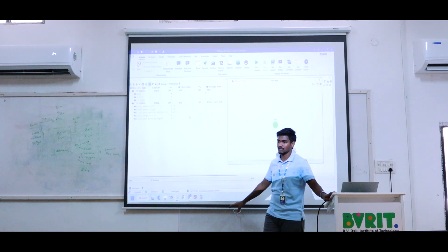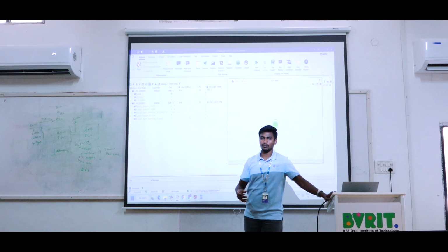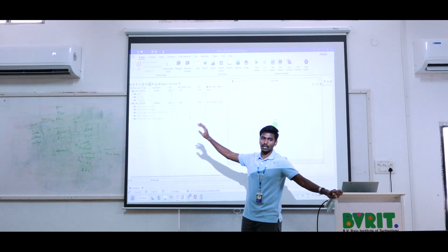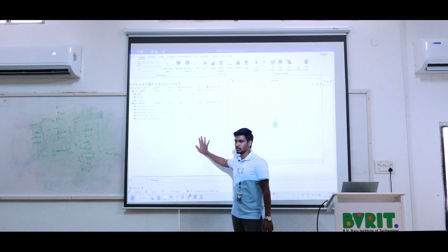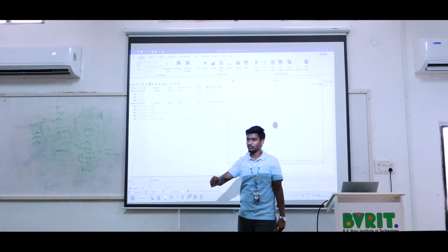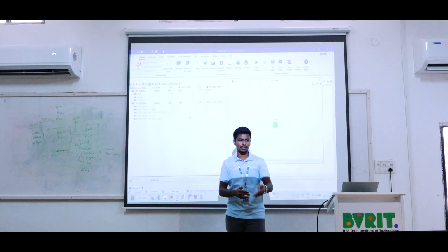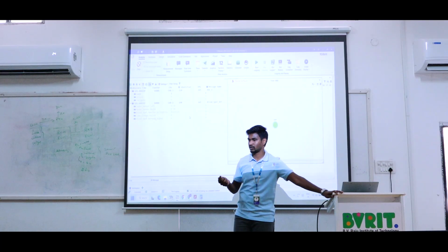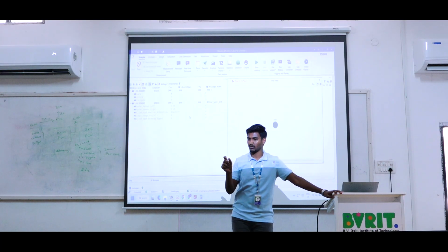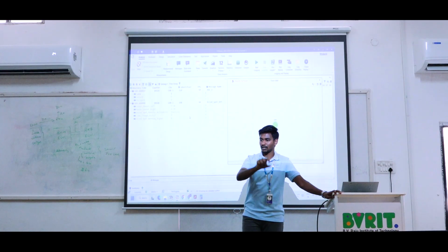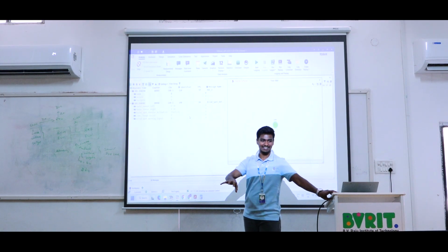That is the functional design, that is the CAN database. If you understood, you are able to create a database, and you can easily access the tool, because this tool works based on the database. What timing value can we set here? After you have created the database, I will give you an attribute definition, just a single line of code. Once you enable this code, we are able to transmit with timing from 10 milliseconds to 1000 milliseconds.